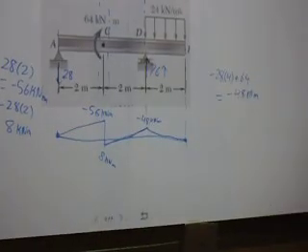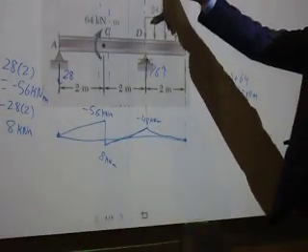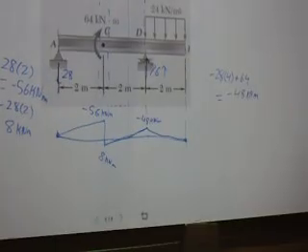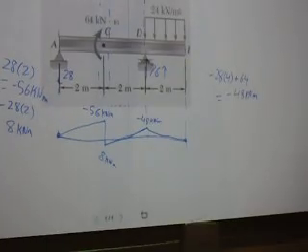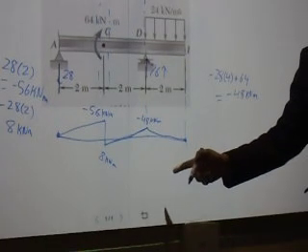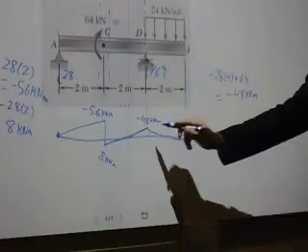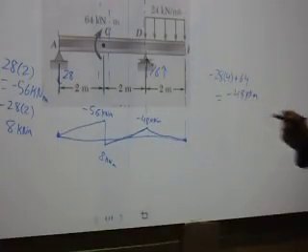So how do we know? Look at the shear. Is it crossing the zero? But there is no maximum here. If this thing was crossing the zero, it would go down like this, and there would be a maximum.